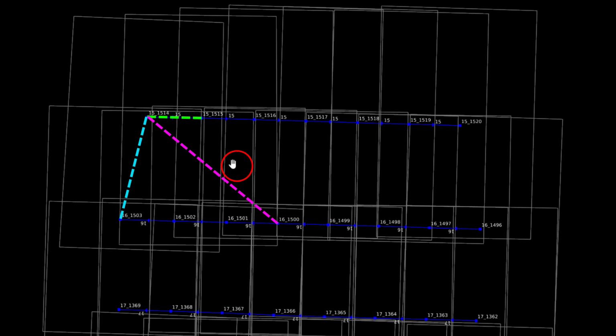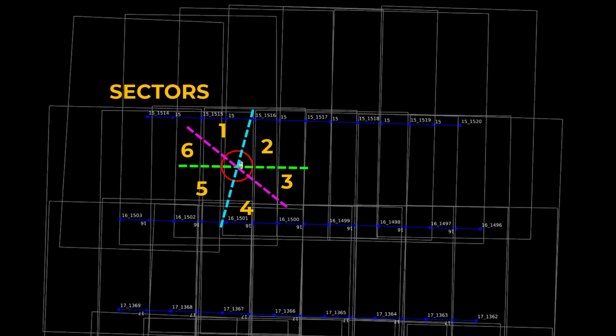So the epipolar line is always in relation to the base of an image pair, and therefore I can look here from different sectors into the same location, and therefore I have different viewing options. I have different epipolar constraints, and therefore I can get different amounts of raw data points for this location to generate points for our point cloud.